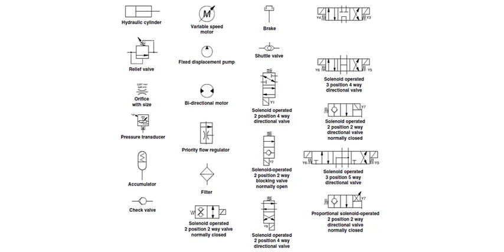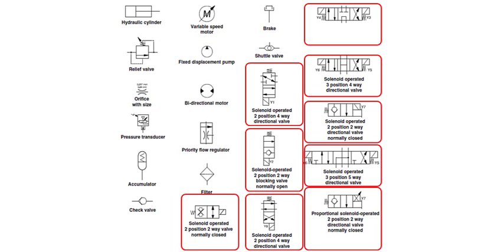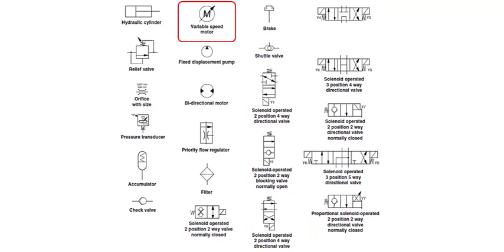This is the hydraulic symbols legend taken from the schematics section of the DC scissor service manual. The hydraulic system utilizes one fixed displacement gear pump, and a number of directional valves for individual functions. The speed of the drive and lift functions are varied by the electric motor that drives the pump based on the operator's joystick command. Genie scissors descend by gravity when the down valve is activated, and the speed is controlled by a fixed orifice located in the lift cylinder port block.